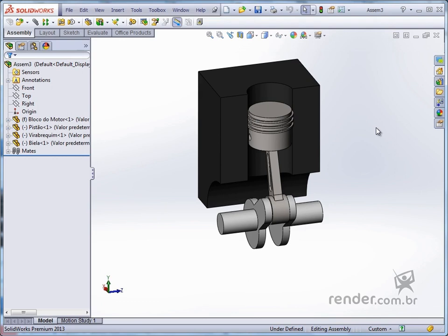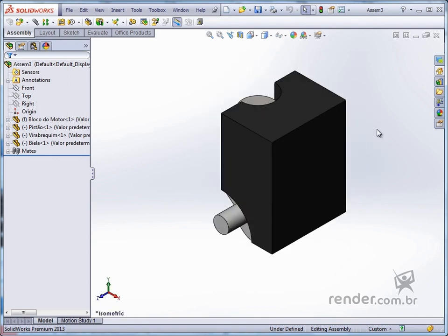First let's make some definitions in the 3D environment. Set the model view in isometric view by typing Ctrl+7, or by using the appropriate command. See that this view does not show all the components of the assembly, so let's create a view to show them, to add later in the breakdown.